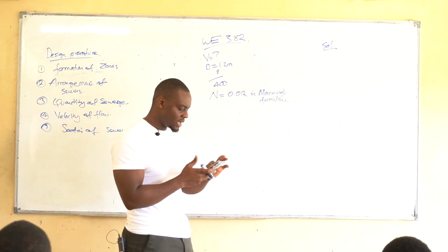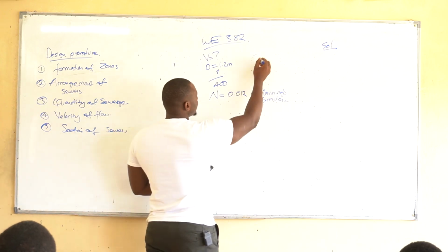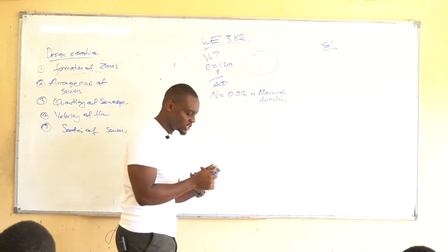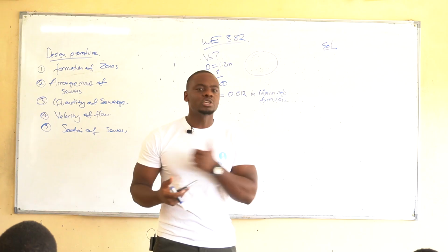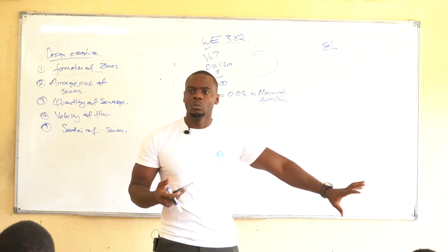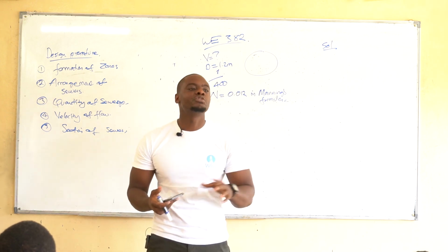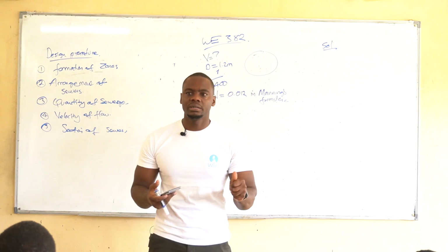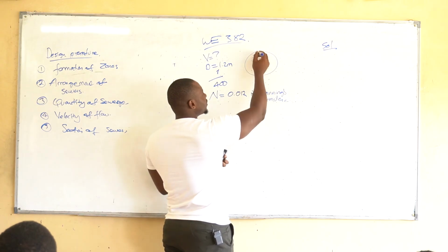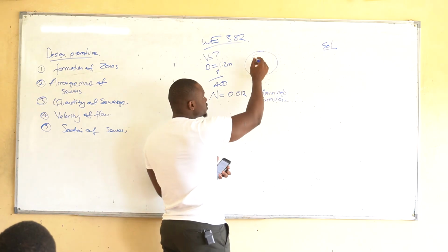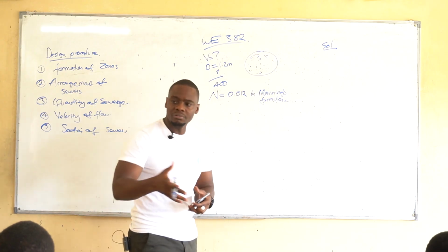I think everything is okay up until we are saying 1/2 full. Probably this is the point that we didn't touch on. If we are relying on gradients to transport fecal wastes, we cannot run that sewer or a pipe at full throttle. You understand that, right? You can't fill it up all the way, otherwise it's going to clog. You don't have a pump, you don't have an energy that is transporting, so you can't fill the whole cross-section of a sewer pipe.